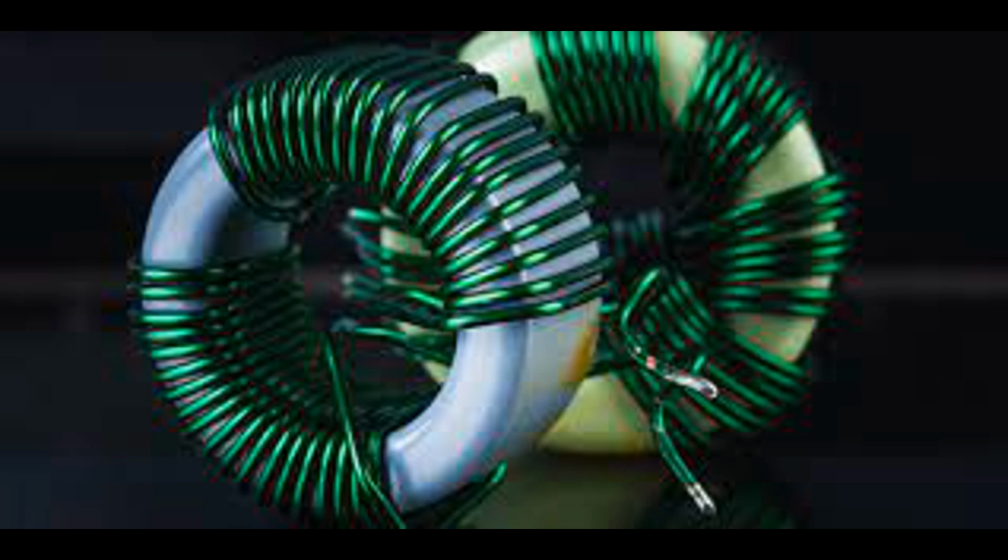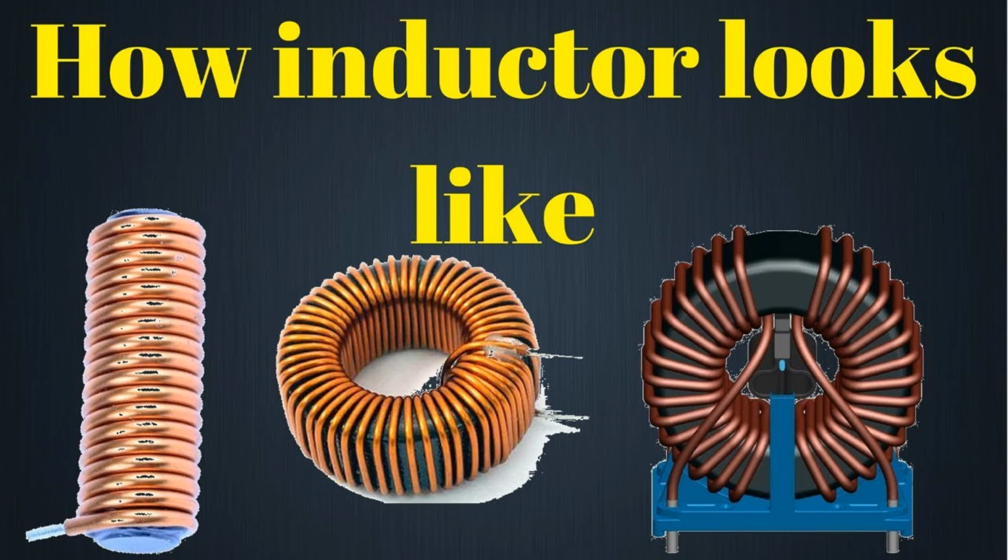Applications of resonance with inductors. Radio tuners. Application: LC circuits are used in radio tuners to select and amplify a specific frequency from a range of broadcast frequencies. By adjusting the values of the inductor and capacitor, the tuner can be set to resonate at a desired frequency, allowing it to pick up a particular radio station. Example: AM and FM radio receivers use resonant LC circuits to tune into specific frequencies while rejecting other signals.